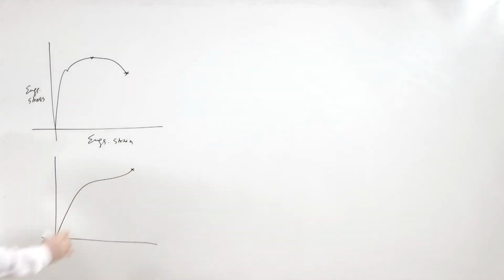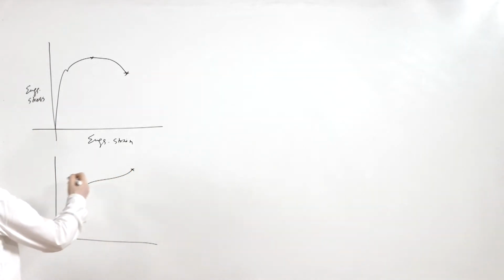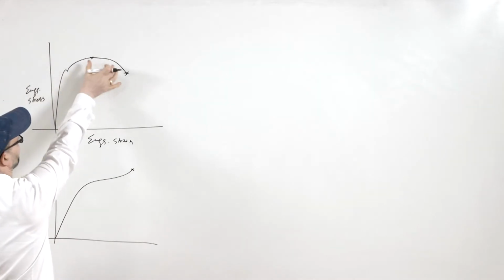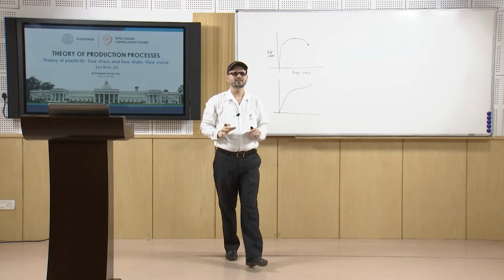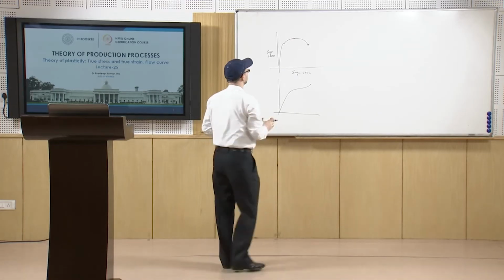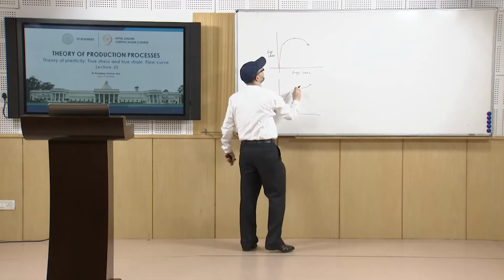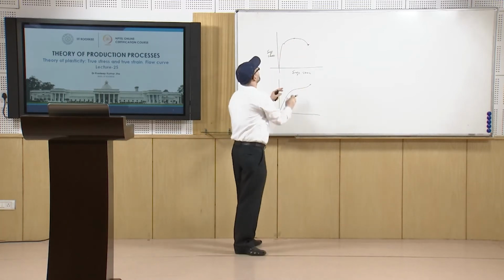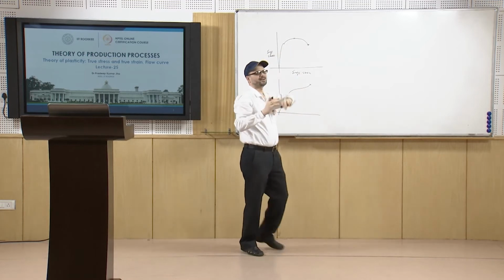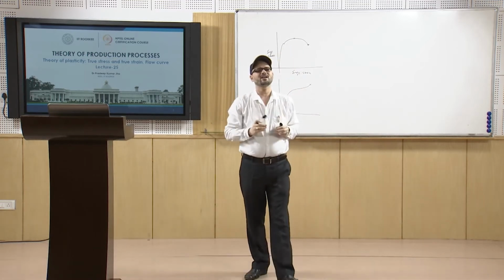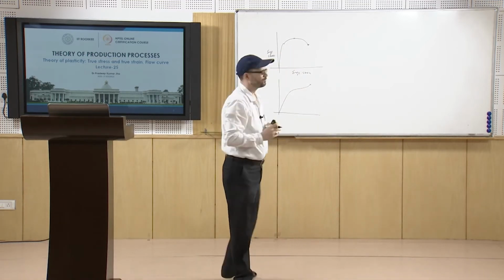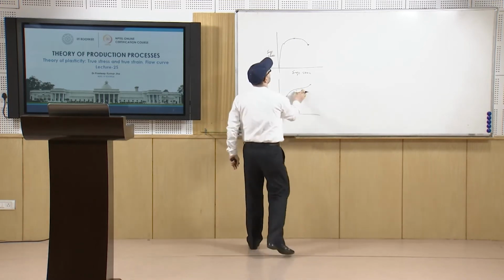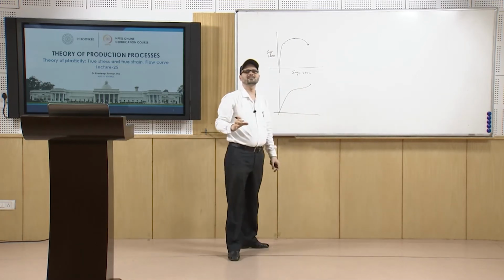It does not decrease basically in the true stress true strain curve, because this is the region where the strain hardening takes place, and also the cross sectional area goes on decreasing. So although the load required is decreasing, the cross sectional area is also decreasing. So that is why stress is basically not decreasing in that sense.